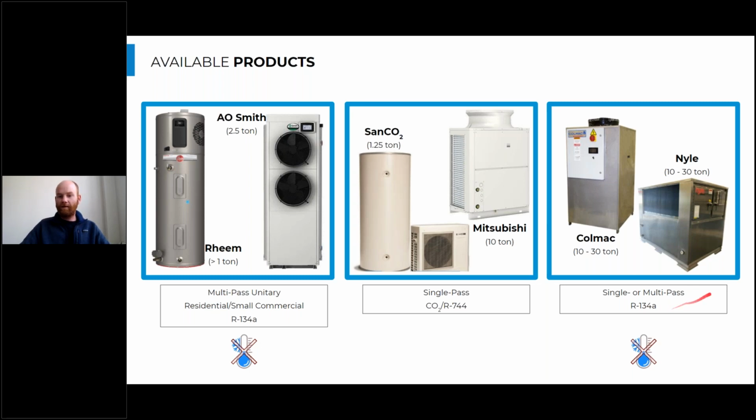But one thing with these two heat pump water heaters is that they use R134A as the refrigerant. And that refrigerant is challenged by low ambient air temperatures. Specifically, once you get below about 40 degrees Fahrenheit, maybe 35 for these newer units, they start losing capacity significantly, and they don't really work at all, or they can't move any heat below that 35 degree Fahrenheit number. And so we had to get clever.